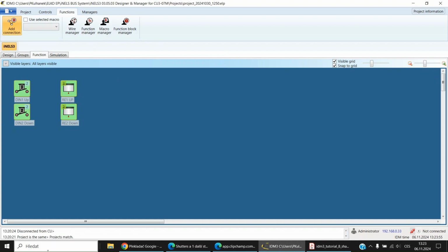In the next example for Venetian blinds with slat tilting, we use relay 3 to move blinds up and tilt slats up, and relay 4 to move blinds down and tilt slats down. To control the action, move blinds up or down, digital inputs 3 and 4 will be used. The example shows using 1 and 5 second long intervals for the pulse. However, in a real project it is needed to measure pulling blinds or shutter up and down to determine the actual time required for the pulse length.